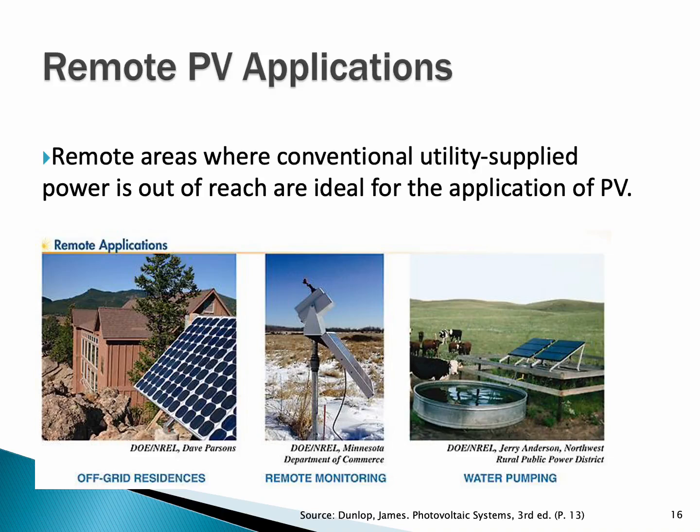Here we have a water pumping system, or an array, out in the back 40. We have a deep well pump. The array powers up the pump and fills up the stock tank, and a float switch will turn the pump on and off. So when the stock tank is full, the pump turns off, and the cattle come, suck it down, then it'll turn back on.